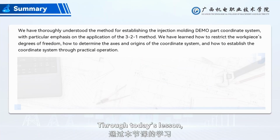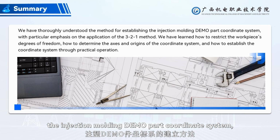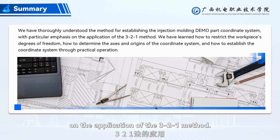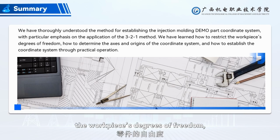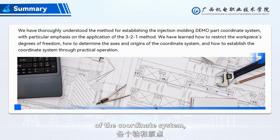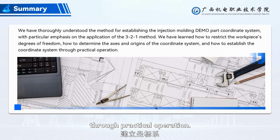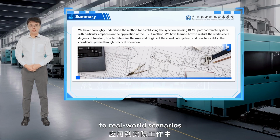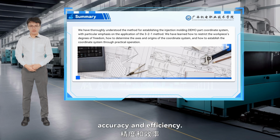Through today's lesson, we have thoroughly understood the method for establishing the injection molding demo part coordinate system, with particular emphasis on the application of the 3-2-1 method. We have learned how to restrict the workpiece's degrees of freedom, how to determine the axes and origins of the coordinate system, and how to establish the coordinate system through practical operation. I hope you can apply this knowledge to real-world scenarios to improve measurement and processing accuracy and efficiency.